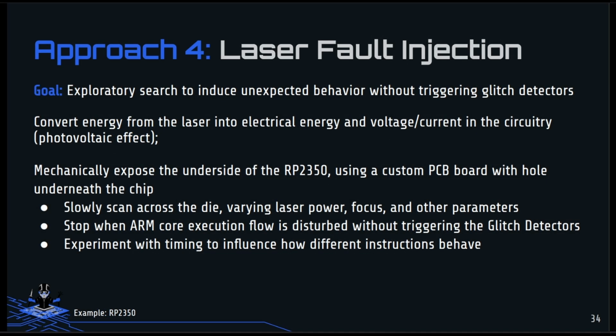Now we're going to move away from some of the voltage and EMFI glitching and actually look at laser faults. So this is a little more nebulous goal up front, where we want to do an exploratory search to see what behavior we can induce without triggering the glitch detectors. The intent is to convert energy from the laser into electrical energy and voltage in the circuitry, which is called the photovoltaic effect. The goal and way to do this is to mechanically expose the underside of the microcontroller,